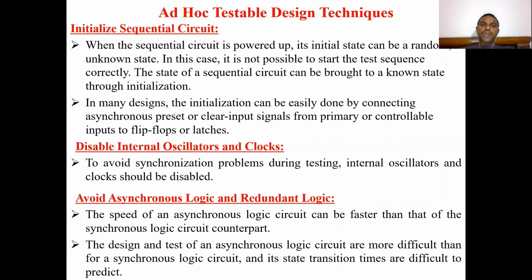That's how you can initialize sequential circuits before applying the test vectors: in many designs, the initialization can be easily done by connecting asynchronous preset or clear input signals from the primary or controllable inputs to the flip-flops or latches. That is how we initialize the sequential circuit.